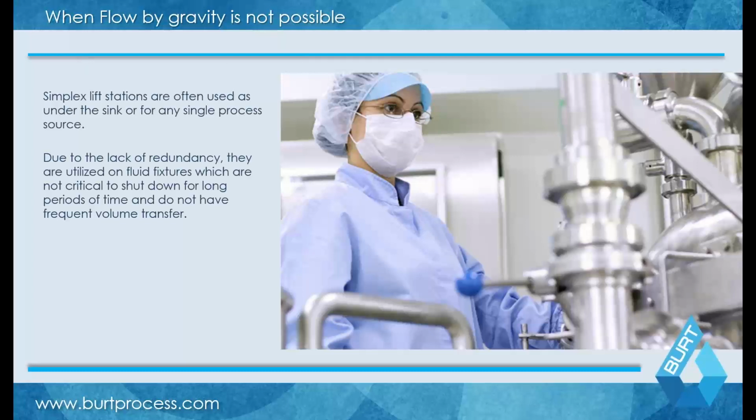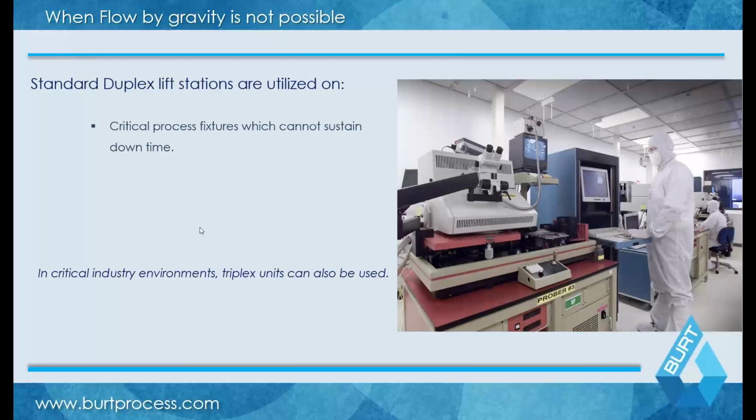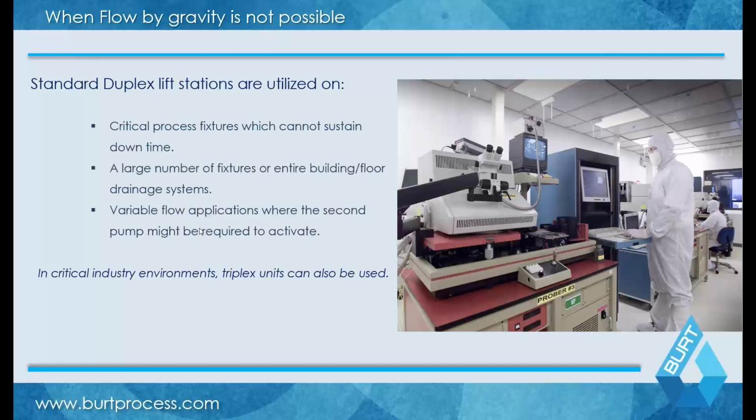That can be a simplex-based design. Simplex tends to be utilized more for smaller applications, laboratories or single sink applications. Duplex you see more when you're talking about an entire building. It's very common, for example, to have an application where you bring all of your waste to a central duplex lift station point and then pump it up into a pH system, if your gravity lines are underground, for example.